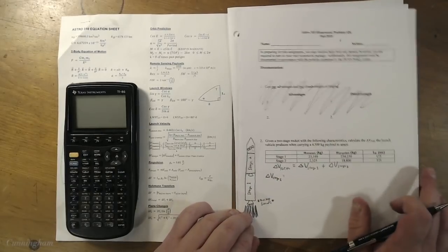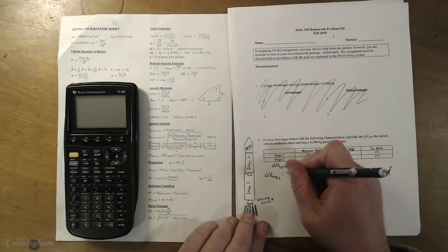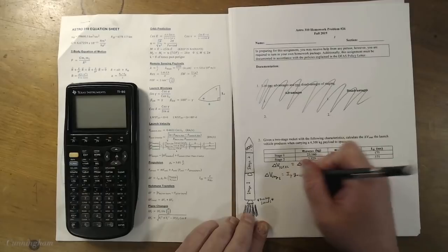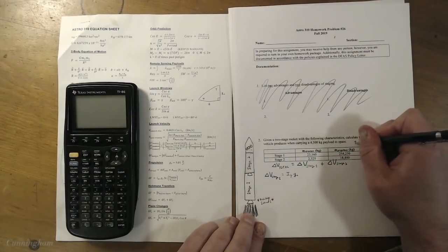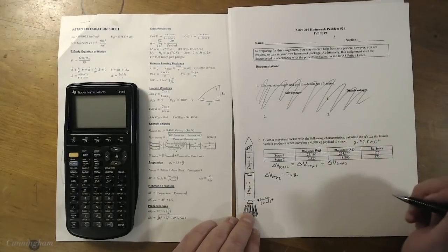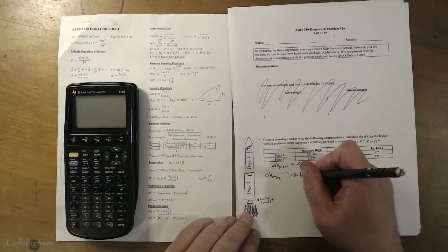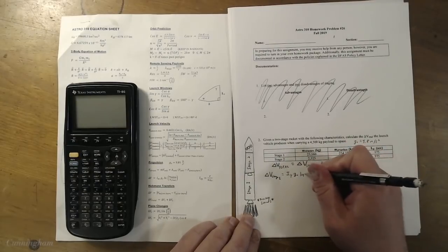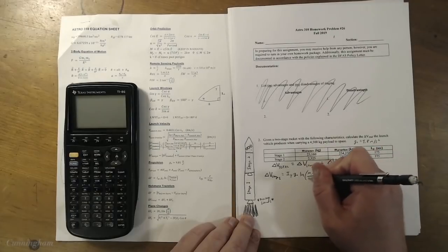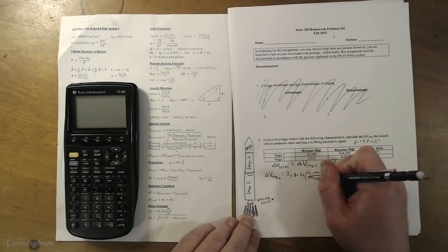What we want to do with that is plug in the ideal rocket equation. So the efficiency of it, the bang for the buck of it, ISP, times g naught, which in our problems for Astros is always 9.8 meters per second squared, basically Earth gravity, times the natural log, or ln, of the initial mass of the stage over the final mass of the stage.